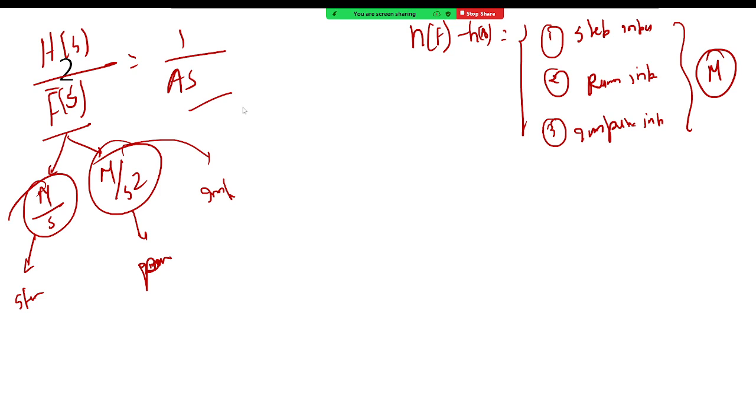So yesterday I discussed the step input, ramp input, and impulse input for a first order system. And I developed some mathematical models for a mercury thermometer as well as a liquid level tank, and a purely capacitive process. Here I derived for a purely capacitive process that H bar(s) by F bar i(s) equals 1 upon s, where H bar(s) is the height in terms of deviation variable, and F bar(s) is the inlet flow rate in terms of deviation variable, right?